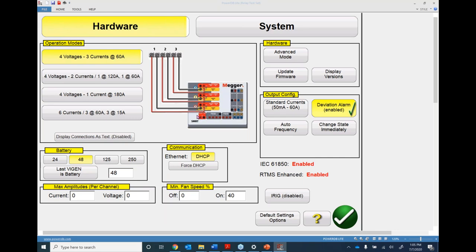So if you need to use currents in a parallel mode to be able to inject a higher value of current, you can choose option second or option third, wherein you're actually now paralleling first and second current and getting a single current output, which is a high current output from here, YGen 1, and then the second current here is taken from the third current channel.